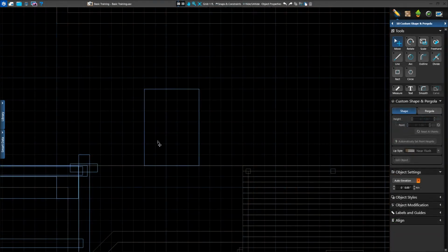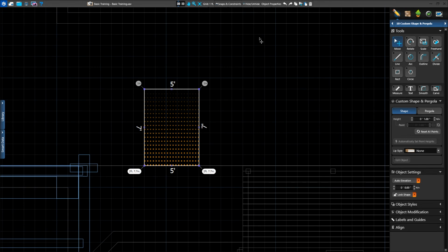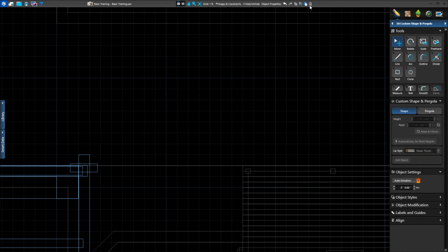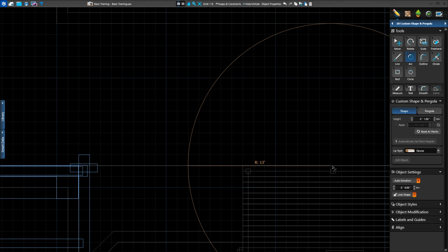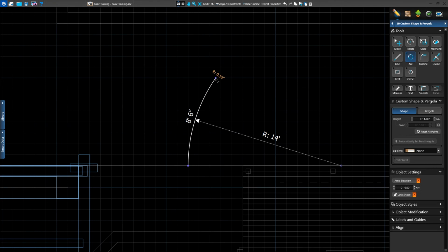Our ramp looks great, but our client also wants to see a staircase surround. No problem. We'll delete our ramp and create this option for our client. We'll start by creating the surround. With the Arc tool, we'll create a 4-foot radius going to the right. Once set in place, we'll draw the arc so that it stops 7 feet from our upper hardscape.